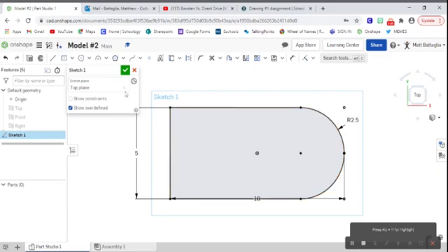So let me go ahead and grab a center point circle, and right at the center of this, I'm going to left click and release. I'm going to drag out, and based off of my drawing, I know that I have a radius of 0.5 here. So I'll select 0.5 and hit enter. I apologize, it is a 1 inch diameter, 0.5 inch radius. That's totally my fault. So we got our 1 inch diameter, 1/2 inch radius circle here.